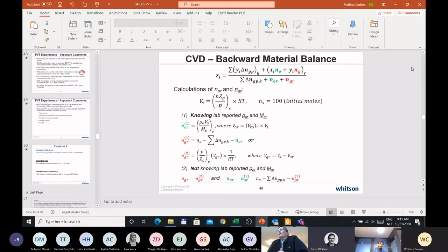What I call relative oil volume, or basically the relative amount of oil and relative amount of gas below the saturation pressure, is such a strong tie to the K values and to the phase equilibria that getting that data is really important. We often get it for gas condensates, but often not for oils. So that's one thing I would argue strongly for. And I think a lot of the labs actually have the data, but they don't report it necessarily. So that would be the top of the list.